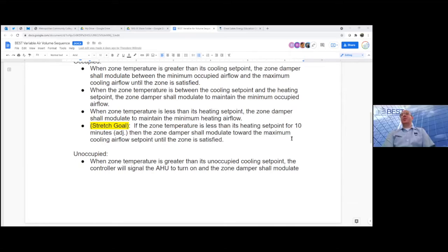One of the things that I know was done for at least a time in Las Vegas, because during the height of the summer when it was the hottest, instead of bringing in outside air to do the air changes within the casinos, they would actually dump in oxygen, like tanked oxygen or liquid oxygen boiling off, into their air handling systems to satisfy those outside air requirements, because it was literally cheaper than bringing in and conditioning that mega hot outside air, because of deciding to build a giant city in the middle of a desert. Anyway, far from the only place we have that concern.